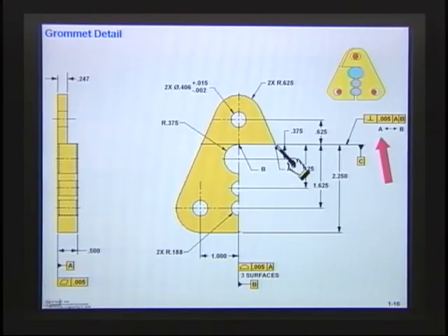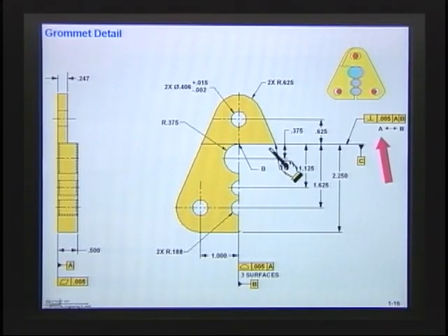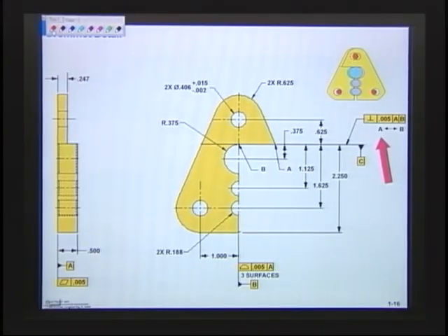All right, so we've got our datums now, and let's see if I can draw that datum reference frame. The datum reference frame, if I was to draw it, this one here establishes our datum, and it looks like it's going to be this face. That was the datum here, and then it was also this face over here.